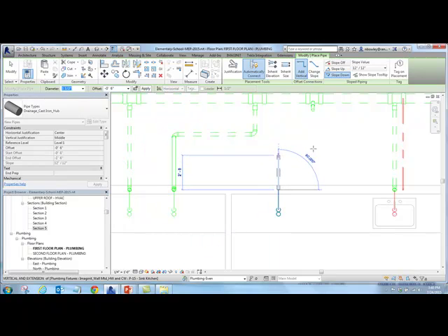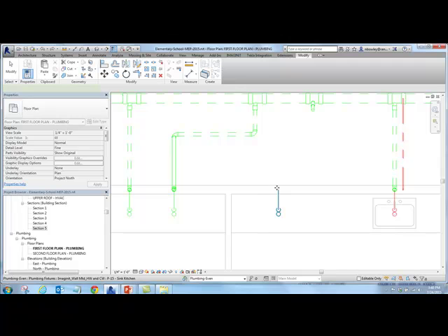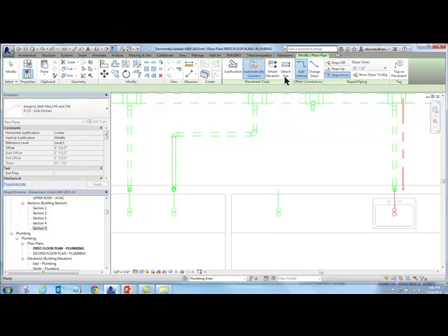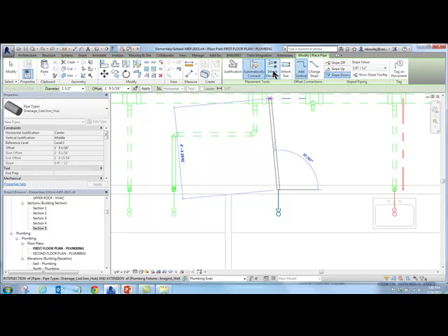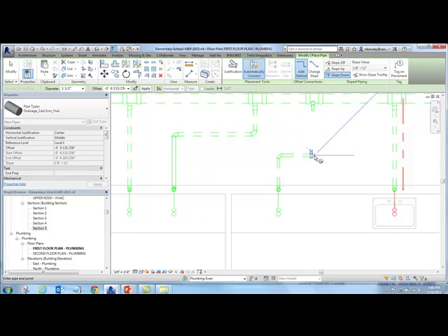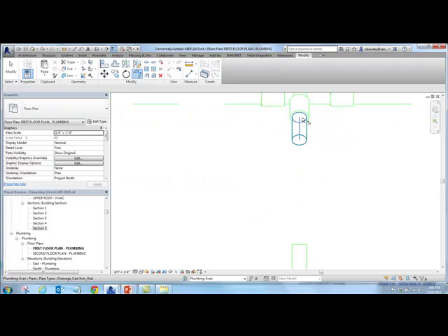And what's that? Oh man, I can't do anything right. I should have just done a PowerPoint. All right, inherent elevation, 1/8 inch to a foot, slope down. I don't need inherent elevation actually. And then -6 inches, not feet. And we'll see how this goes. I know I missed. All right, let's align the two just because I misclicked. And then we'll do trim and extend to corner, and hopefully this works.